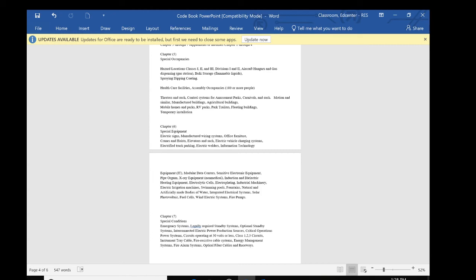Need to know about that because we do a lot of temporary. It's about everything that we go to. You're an electrician, they want you to get temporary power. So for a house, usually it's just a T-pole. Hopefully it's hooked up, it's good. If not, sometimes you gotta have a generator. And then if you're doing multifamily, it's gonna be different. It's probably gonna be a lot bigger temporary generally. If it's a wrap or a podium type, if it's a bigger one, you're gonna have to put temporary throughout the building. So it's gonna be important to us.